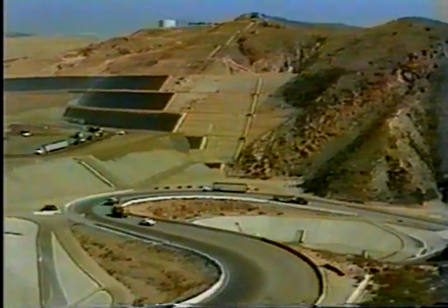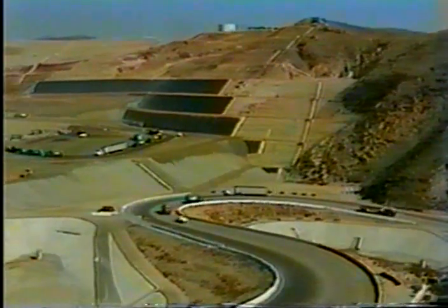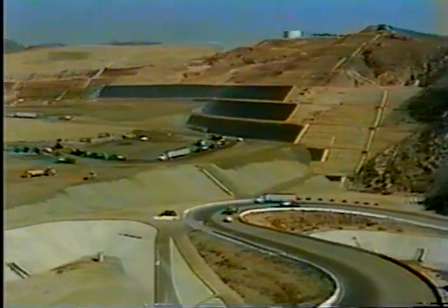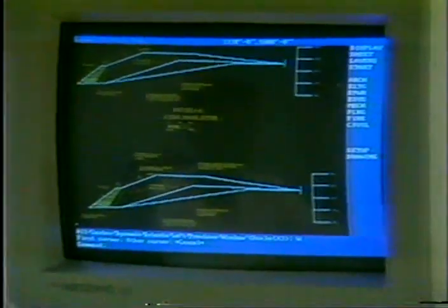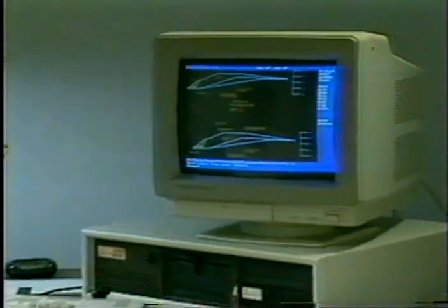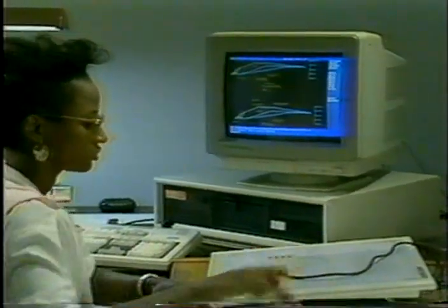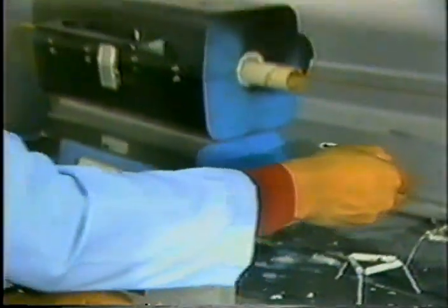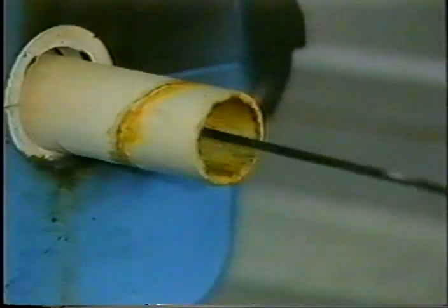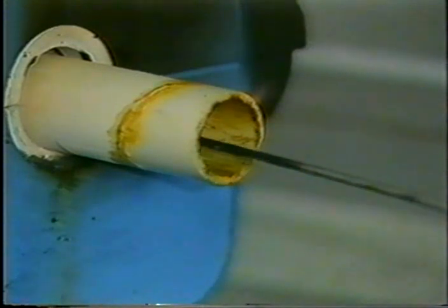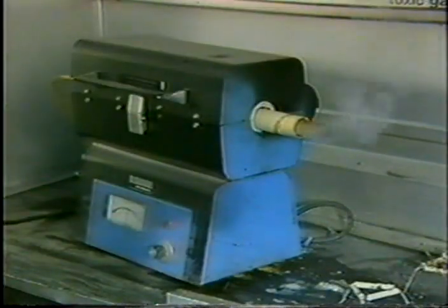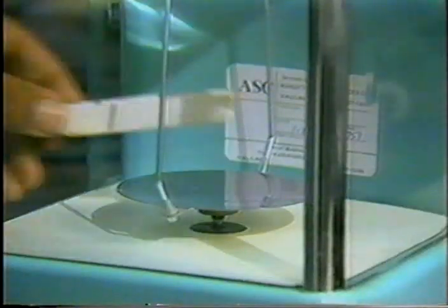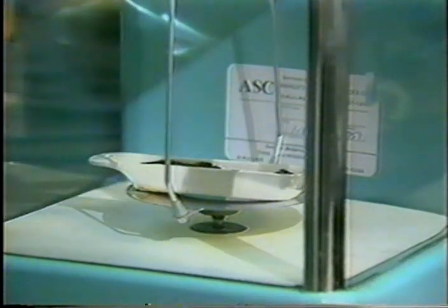However, each landfill area is unique. Each site has its own geometry, soil types, climate, and waste characteristics. Design must be site-specific. Once the design requirements have been defined for a particular site, materials must be evaluated against the required properties. This evaluation will be according to accepted analytical methods, calculations, and procedures based on laboratory testing.